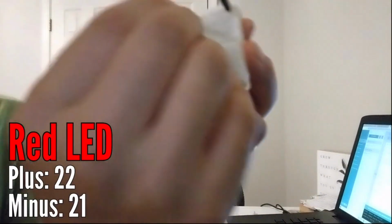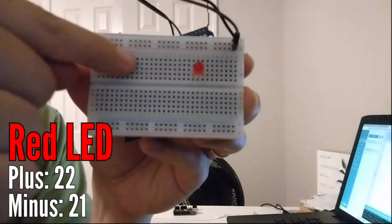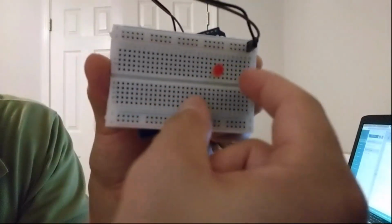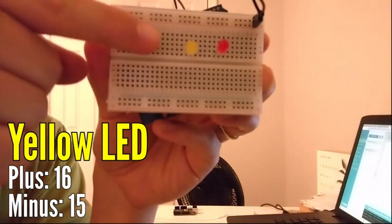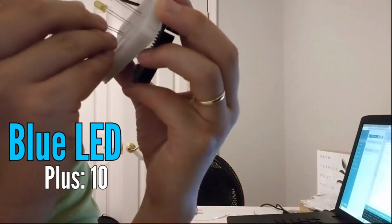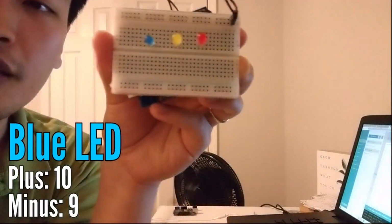I'm going to put the red LED positive at 22 and negative at 21. You'll see numbers 1 through all the way along the top if you look at the breadboard. You do not have to use these numbers, but that's what I'll be using if you want to follow along. We'll do the same thing for yellow: positive 16, negative 15. Always positive to your right, just to be consistent. And the blue one or green one, positive to 10 and negative to 9.